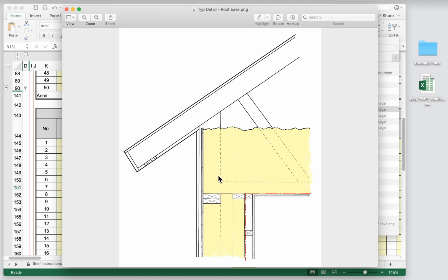And so notice here also that the team wants to use a raised heel or so-called energy truss, right? That's a common technique in wood framing for high performance buildings. And what that allows you to do is get this vertical offset in your truss so that you can get full thickness of your insulation all the way to this outside face.